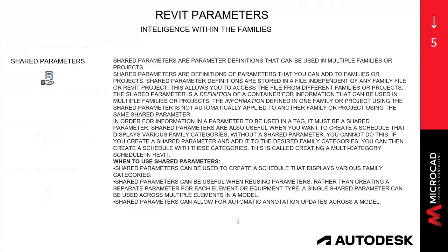The huge advantage of the shared parameters is that they allow me to create schedules where I can display different family categories through a multi-category schedule. They allow me to reuse parameters across different projects and across my whole organization over the life cycle of my organization.